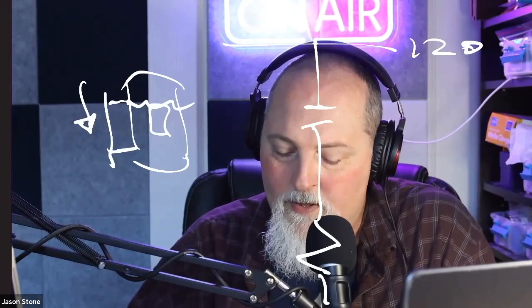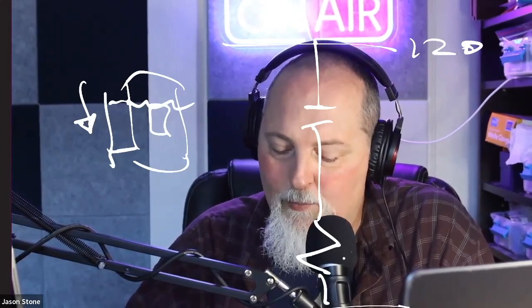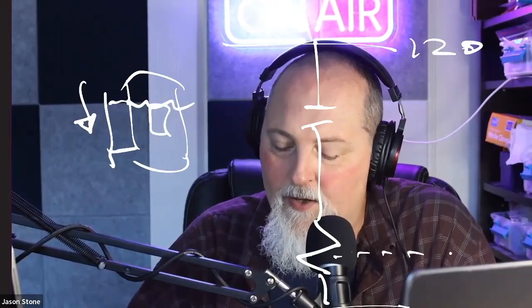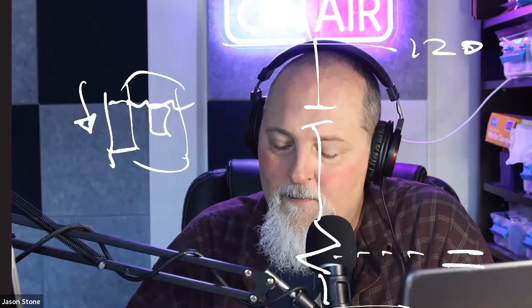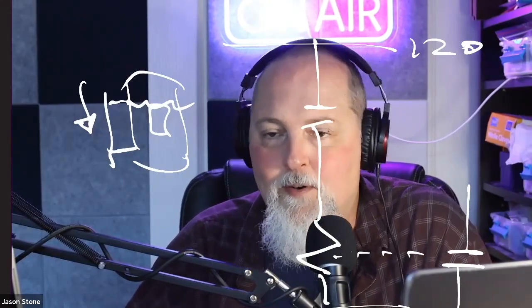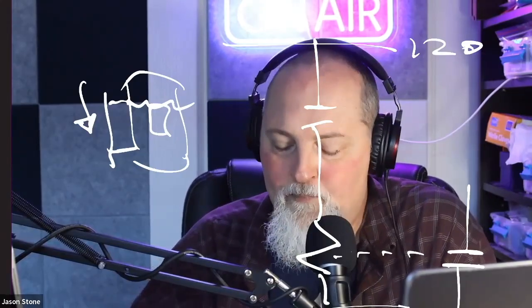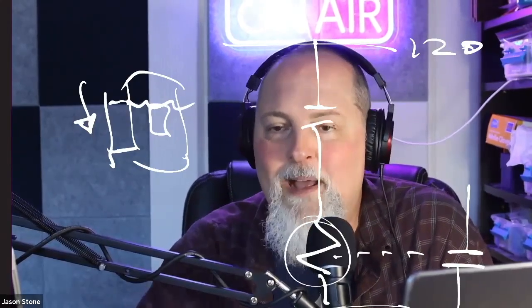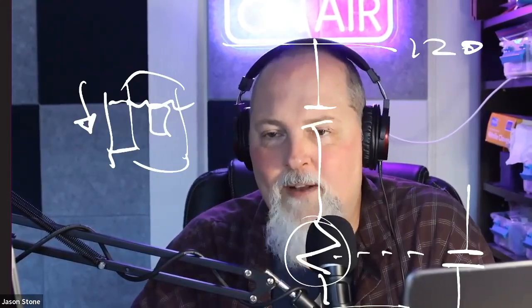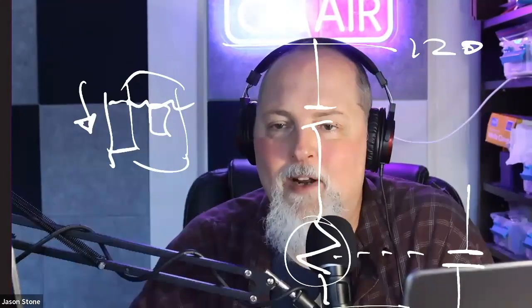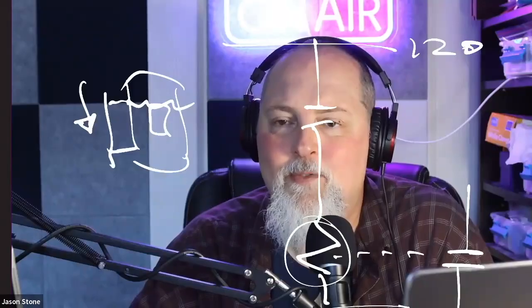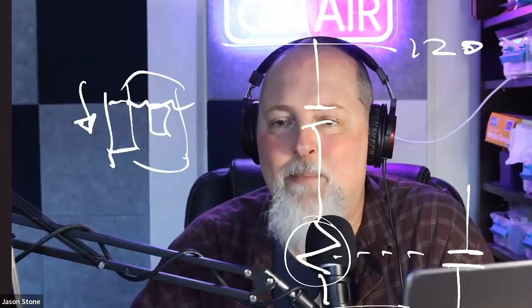There we go. And this relay powers this other contact over here and causes an actuation or isolation, something like that, right? What if this relay just goes bad? We'd have a scram. We'd have an isolation. We'd have actuations. We'd have things happening that we don't want to happen.